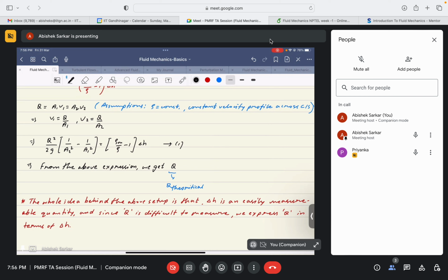Okay. For solving any fluid flow problem, you need to take into consideration mass conservation, momentum conservation, and energy conservation. These three things would be conserved and should be conserved in any fluid flow problem. And the moment you told me that the mass of the water is reduced at the exit because of friction loss, I thought that this approach is wrong, because mass cannot be reduced. Mass has to be conserved. But there can be a reduction in the mass flow rate. Q exit can be less than Q inlet.